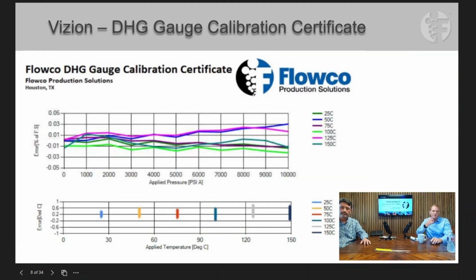We have someone asking, what installations is this applicable for? Good question. That's something we'll talk about in a few slides. But the typical applications that we see with a live downhole gauge are primarily with artificial lift. So it would be to measure your pump intake pressure on a PC pump, which is a progressing cavity pump, or a sucker rod pump.